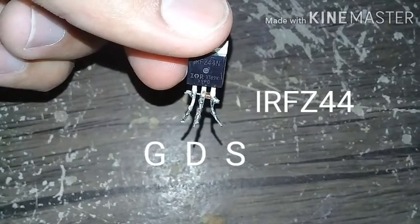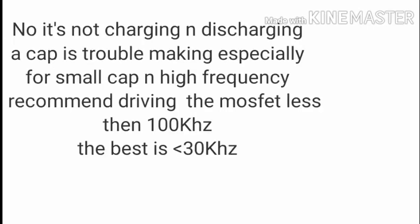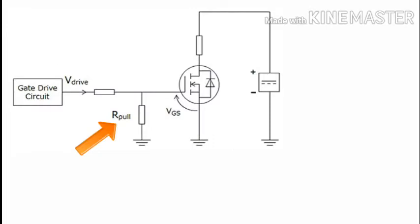As you know, capacitors store energy. If you want to use the MOSFET at high frequency, there will be a delay in turning off. Discharging a capacitor is simple. Use a 10K resistor in parallel with the Zener diode.